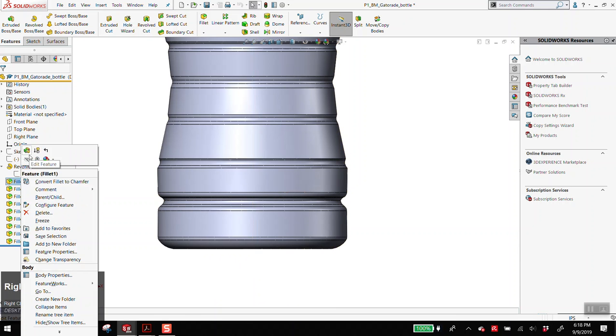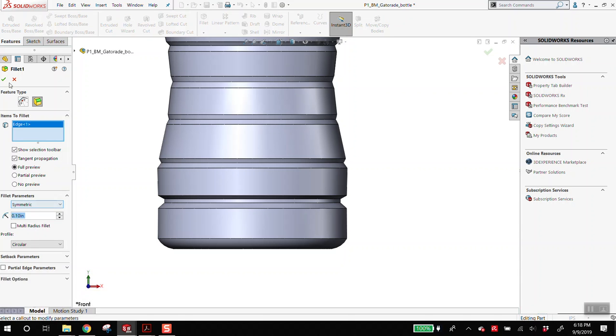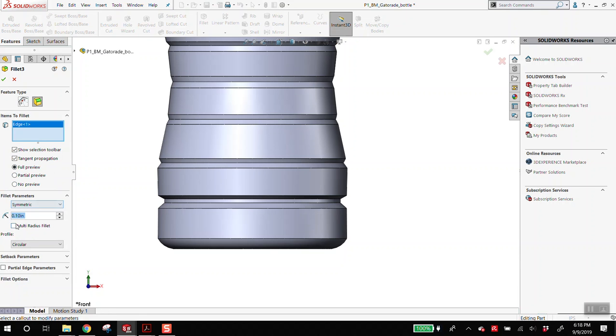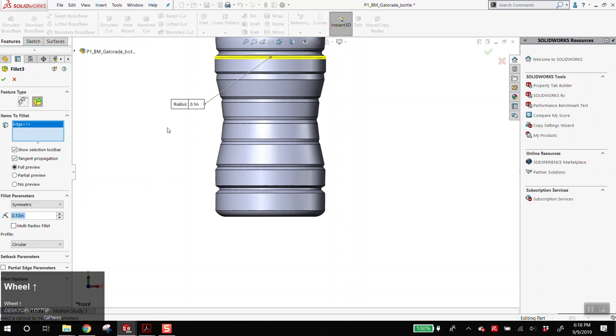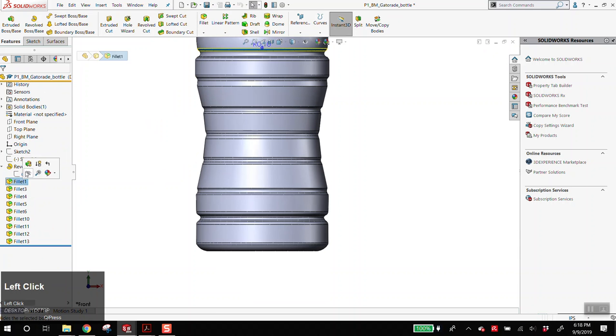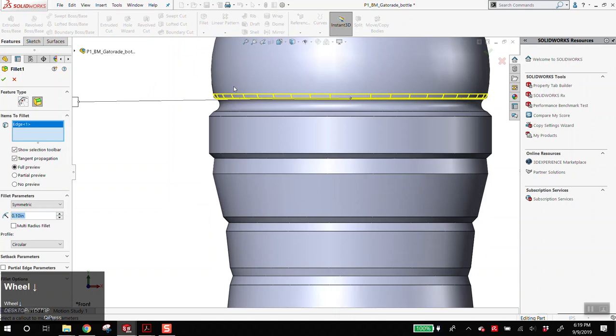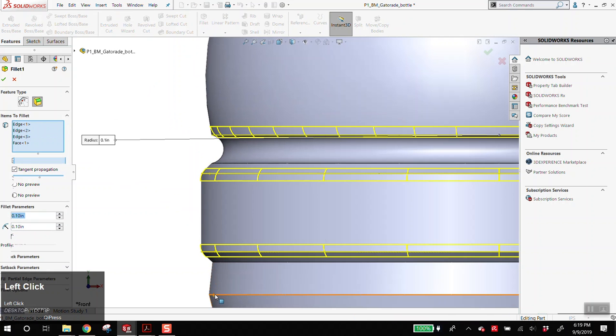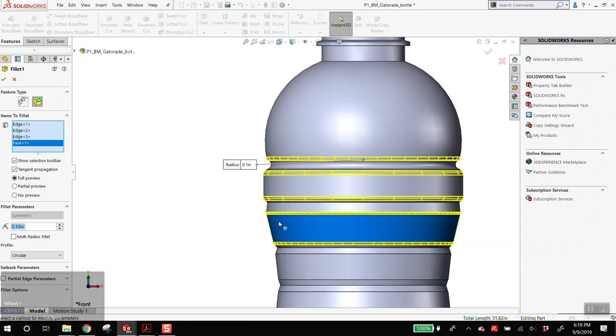And in fact, from an efficiency standpoint, let's see this. You have this set at 0.1. Let's see this one. Okay, so you should be selecting multiple edges with your fillets. Does that make sense? Anything that's 0.1, just select that edge. The only time you'd want to break it up with the same measurements is if the fillet is hitting itself and causing you problems. But if I take a glance at the approach you took with this fillet up here, you could go ahead and select this edge. I don't know, this is a design judgment, but probably all of these edges, or I accidentally clicked this face, but you could do that too, it would save you time.